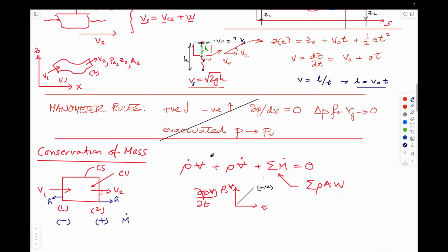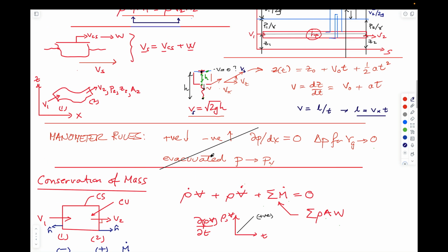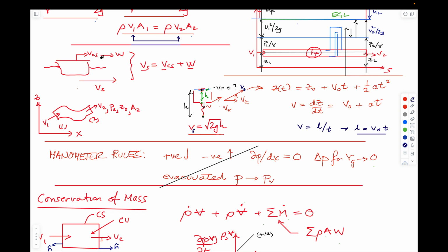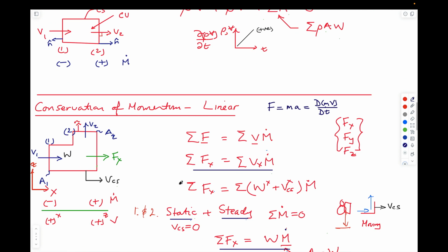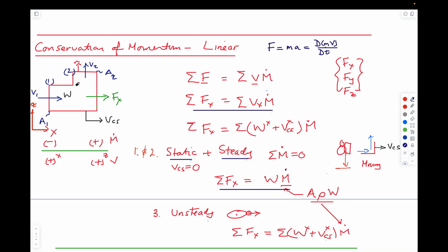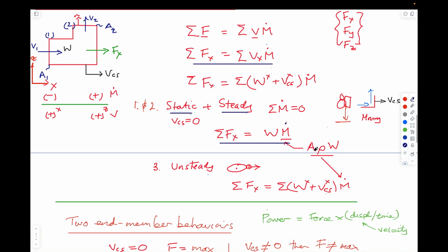In other words, for our Fire Department of New York system, this was the velocity coming out of the hose. So it'd be the velocity coming out of the sled in this particular case, or going into the sled. And of course the mass flow rate is just equal to the area times the velocity, which is a volume per unit time, multiplied by a density, which is a mass per unit volume. So that comes out to be kilograms per second.